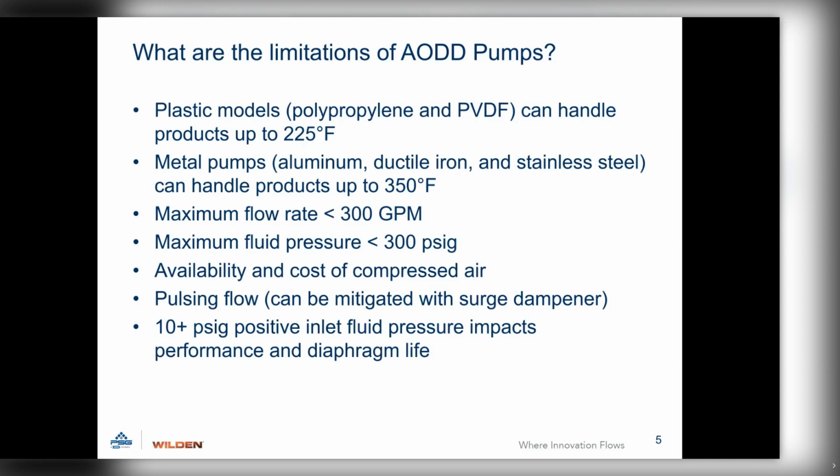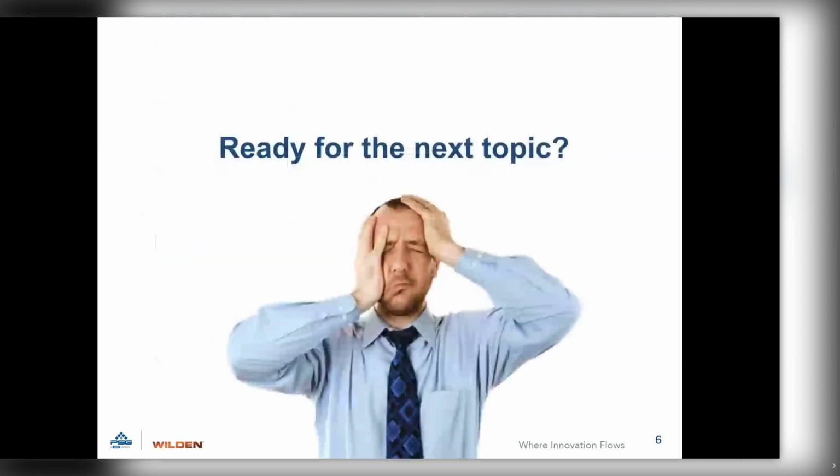So this is why people look at a diaphragm pump, because whatever the product comes into the pump as, it also leaves the pump as that same product with very minimal shear. Only when the ball is coming down on the seat will it change that product being pumped. So, easy enough on the understanding of the basic workings of a diaphragm pump, right? Nothing has really changed on that pump since 1955 when Jim invented it, other than ways to make the pump more efficient or use less air to get the maximized gallons per minute.